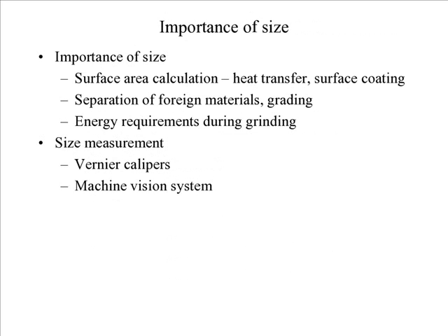So you may be asking the question, what is the importance of size? Well, size goes into your surface area calculation, which has an impact on heat transfer and also if you're coating the surface. Also, you consider the separation of foreign materials, which goes into grading, and you have energy requirements during grinding, which is important in terms of size.